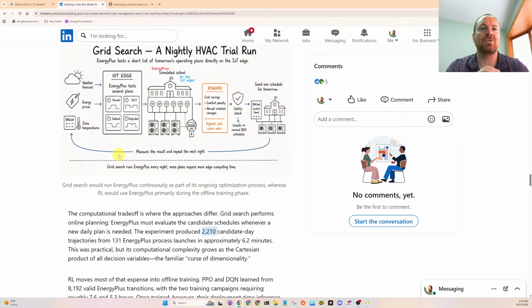I want to get into this too at some point. I want to experiment more in the future with reinforcement learning on a chiller plant, which I think is a good fit for reinforcement learning, where you would be doing expensive, heavy compute every 5 minutes, optimizing for kilowatt per ton. You'd be playing around with pump speeds, chiller and cooling tower staging, fan speeds, that type of thing.